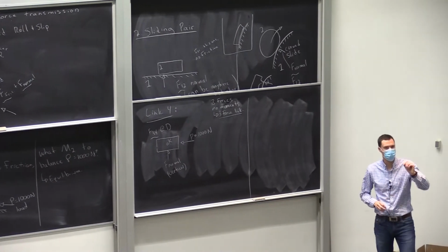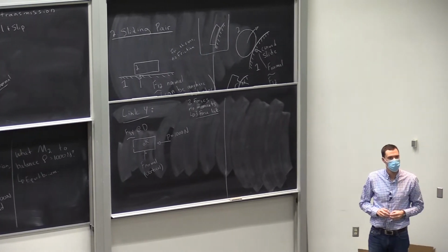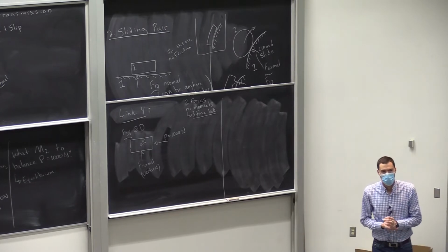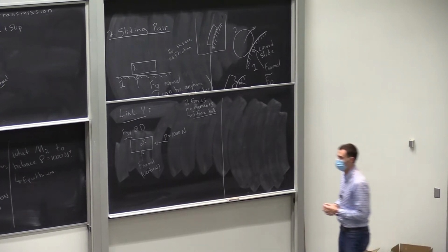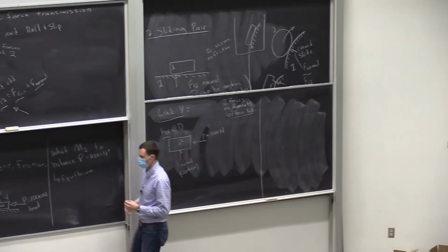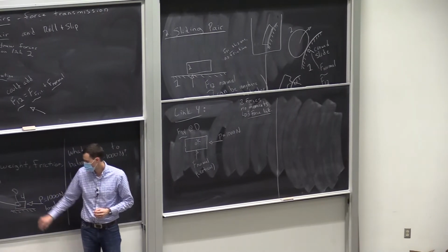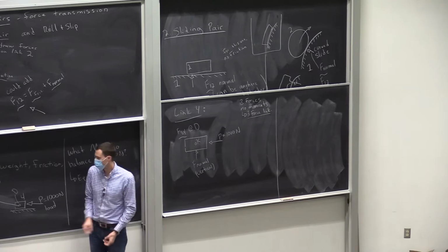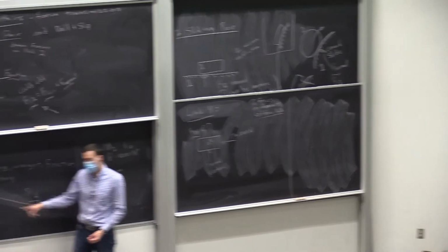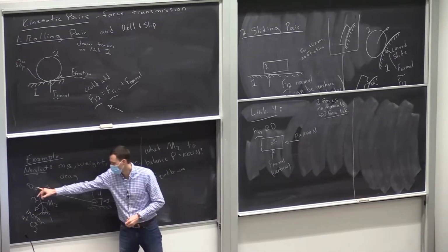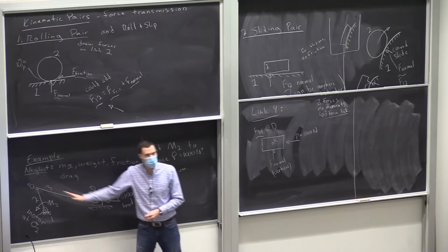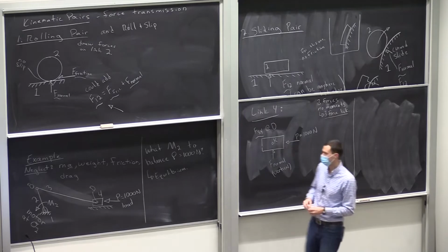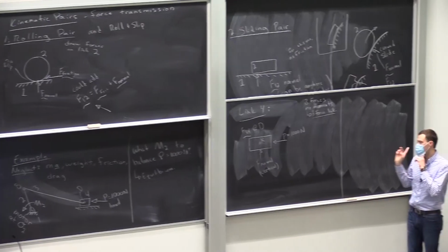Was there a question, or maybe I answered it? Yeah, no, I mean, now that we know, that kind of answers the question, but from before, if we just looked at the mechanism, could we already assume that the force, or F3-4, would act in the direction of 3? So you're jumping to link 3, which is nice. I like that you're doing that, and you're saying link 3 should transmit right along its length, and that's correct. We'll draw it out here.